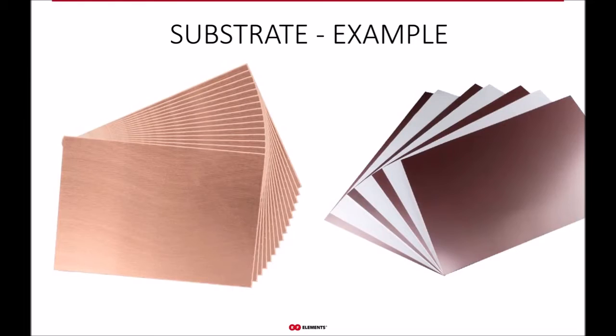This is how typical substrates look. It's a thin sheet of a semi-rigid material with copper metallization on one or maybe even both surfaces. There are many types of substrates with varying quality and properties, with prices spanning quite a wide range. So naturally, the very low loss and precise dielectric constant substrates tend to be on the more expensive side.